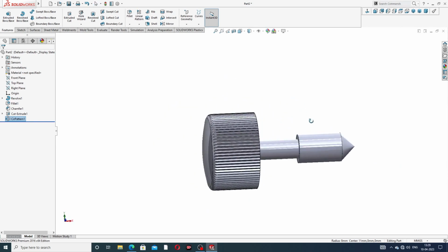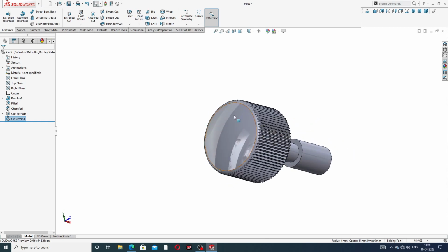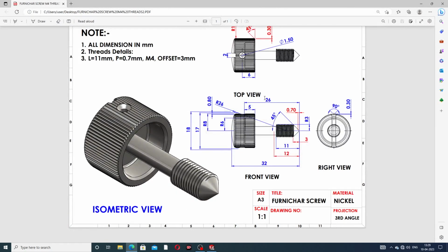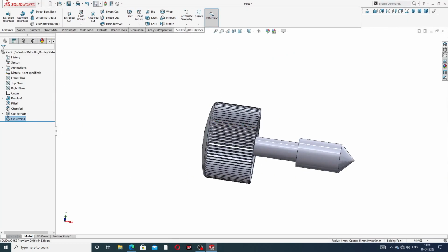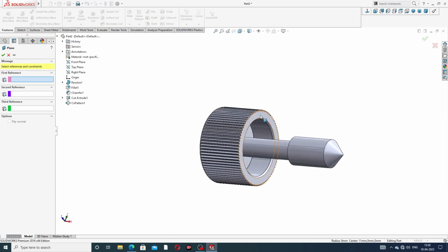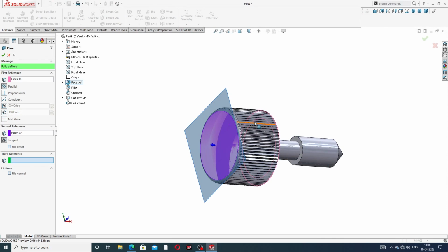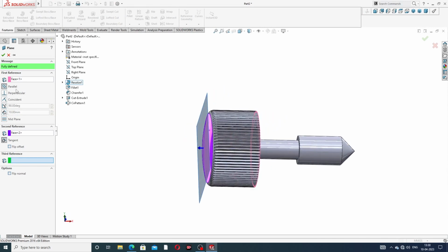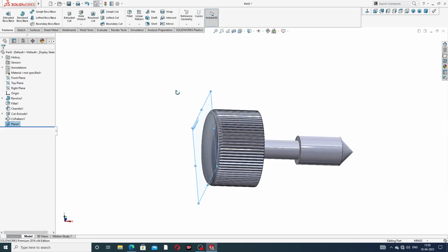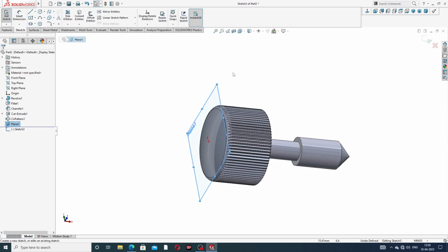And some important points to discuss here. This is a cutout, and this cutout is perfect. Okay, this is 7 millimeter in the inward direction, and a plane is created here. Okay, click plane, select this and use this. Okay, and for this plane use two relations, parallel and tangent, both okay, and select this line and sketch normal.